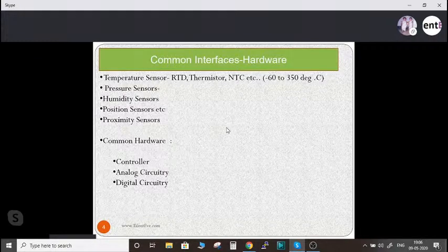Then I need analog circuitry with an op amp. I'll select an op amp interface and connect it to the analog input. And maybe I'll be routing to an LCD display or something, which I will give an output and connect to an LCD display. Same temperature sensor: if I go into the automotive sector, my range may vary from minus 40 to 85 only, which is different from my industrial segment.